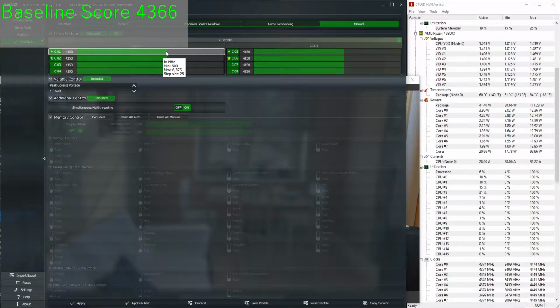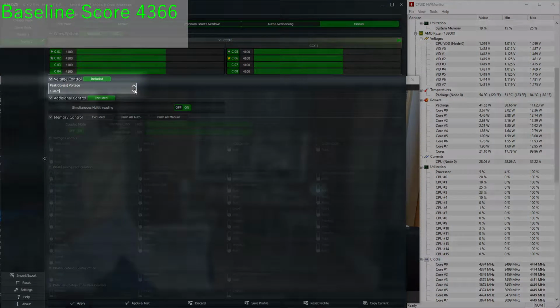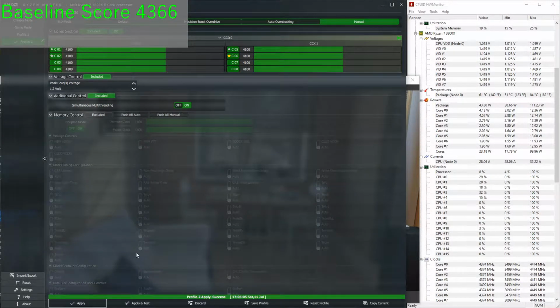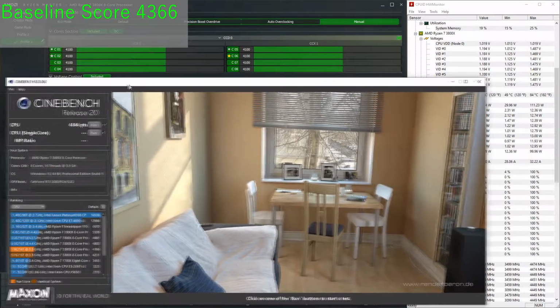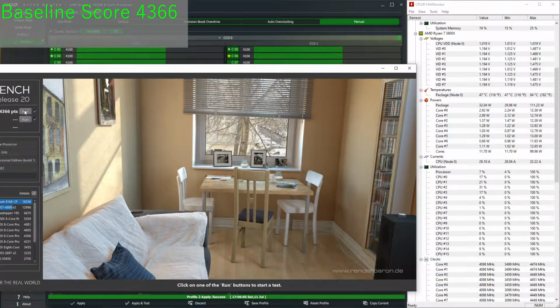My suggestion would be to discard the 4.05 GHz and go to a nicer 4.1 GHz, as that would start us off with a slight performance advantage, and tweak the voltage by going off what yours has presented. The tweak would be started at 1.25 volts in my case, and I will shave 0.05 volts off of that to land at 1.2 volts, at which point we can let Cinebench do its thing.